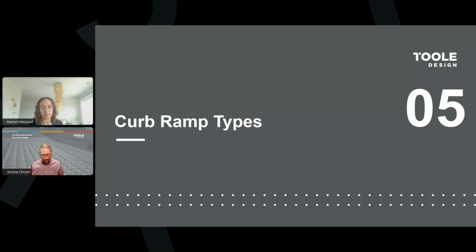And so, because there is a legal crosswalk there, it would require either the provision of the curb ramp, even if you're not going to mark the crosswalk, or the landscaping with the no pedestrian crossing sign. Thank you very much for that clarification, both of you.